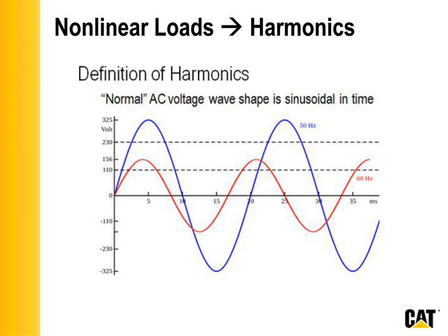SpecSizer is a global tool. It's available for 5 world regions. It's available at 60 hertz in North America and Canada, and 50 hertz pretty much for the rest of the world. Areas of South America and Saudi Arabia are 60 hertz as well. But you can choose up front in SpecSizer whether you want to size a 60 hertz or 50 hertz project. There are ways that the tool automatically mitigates the harmful effects of harmonics and distortion, and I'm going to talk here in a minute about ways that you, the user, can mitigate the harmful effects of harmonics and distortion.